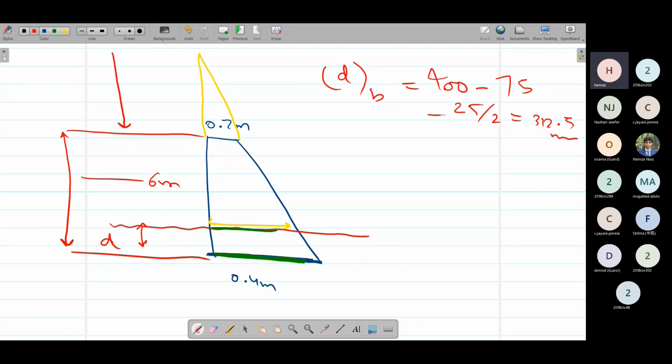So in how much length would it go from 0.2 to 0? Again, it would be 6 meters. You can also calculate this by similar triangles, assuming this value as x and comparing these two triangles. But in this case it is clearly visible that the thickness becoming half in some length, for example 10 meters, then from half to 0 would again take 10 meters. That is simply obvious.